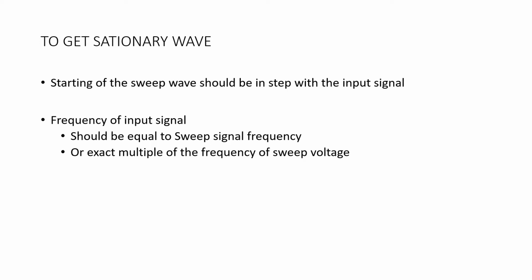In either case, the stationary waveforms are obtained by varying the variable sweep control. This control sets the sweep signal frequency to integer multiples of the vertical signal.